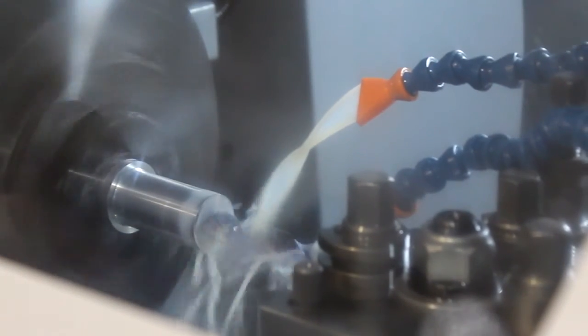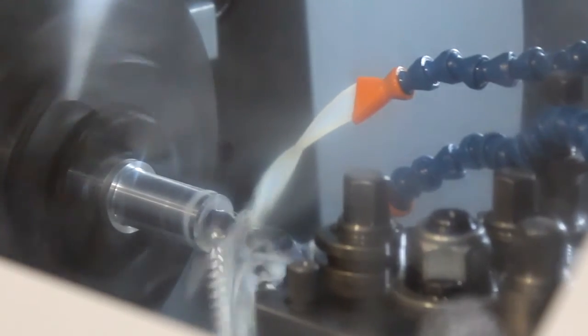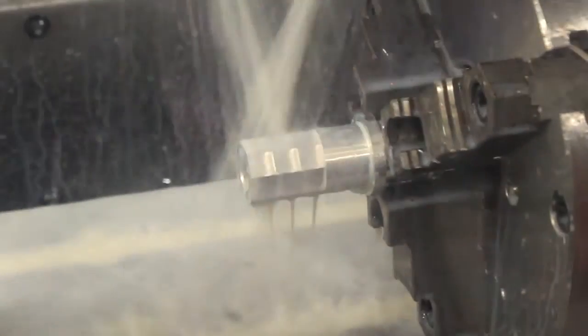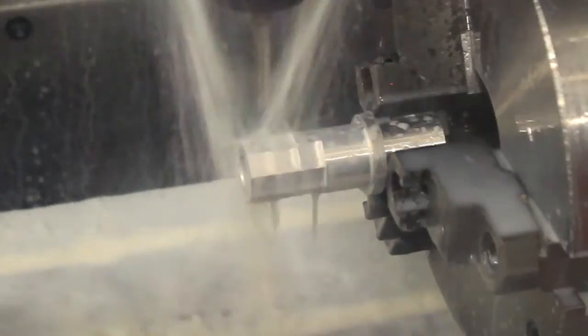The key was manufactured from a circular stock of aluminium. Using a CNC lathe, the shaft hole was formed and it was reduced down to the desired diameter. Following that, the workpiece was transferred to another CNC machine, the VTC 200C, and given its octagonal shape.